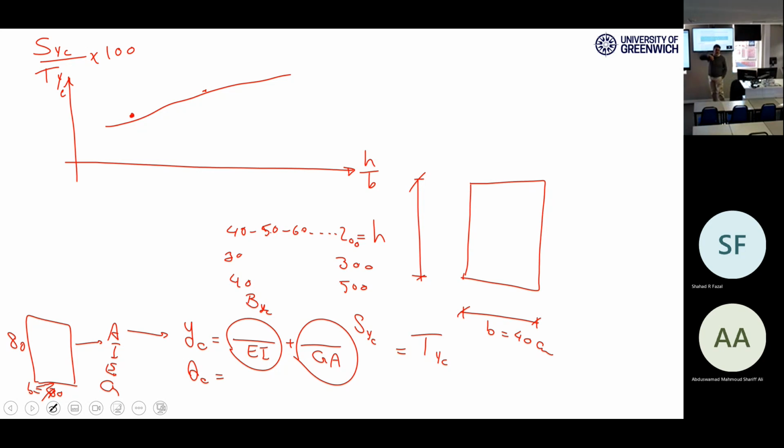In A8, you need to discuss where it is important not to neglect the shear force contribution to the final deformation. It means that in those cases we are not allowed to follow methods like integration methods that only consider the bending moments. We need to go for energy-based methods like virtual work or Castigliano.